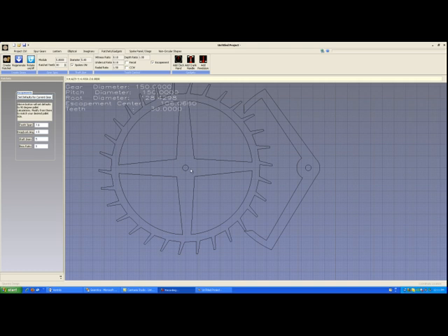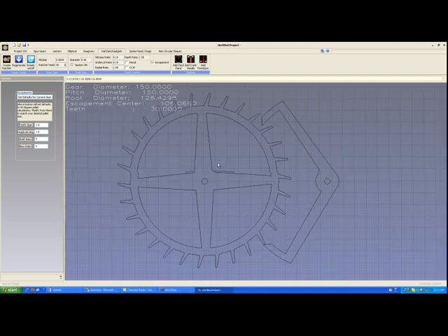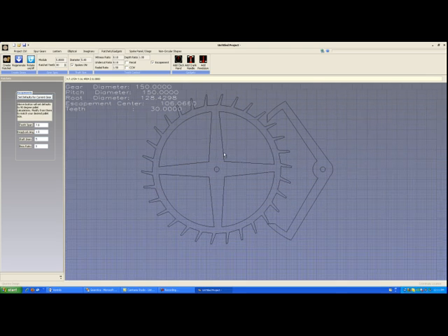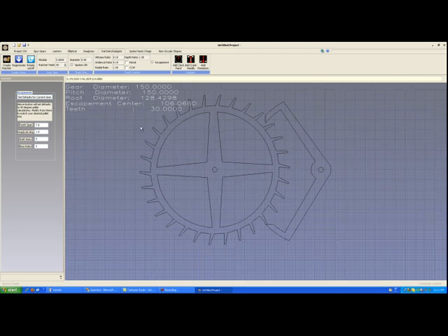The other most important thing to remember is the center distance between the pawl and the deadbeat has to be very accurate. So you should use Gearotic Motion's output of shaft center when you're designing the face of your clock, and we can go into that a little later on. Let's look at some of the variables that we have.